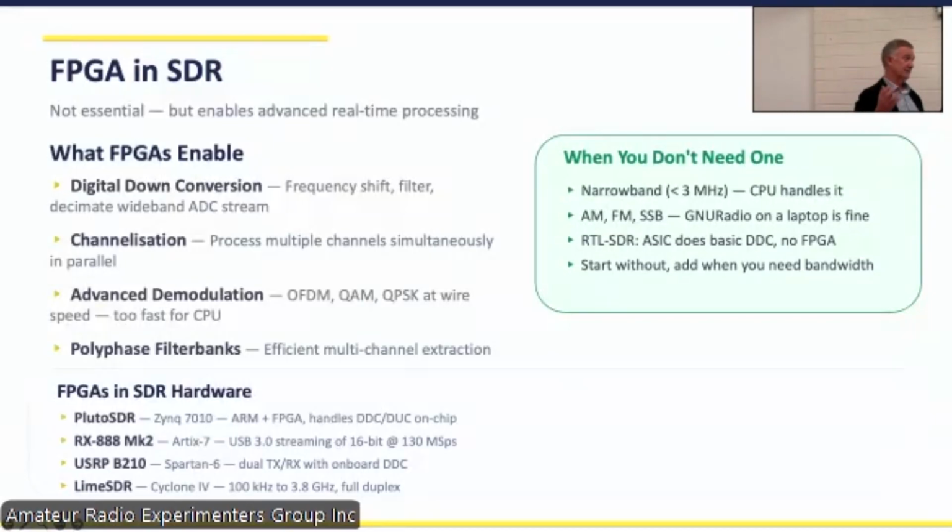If you want to take a 1 gig signal that, say, has 100 megs of data on it at the top, so from 900 through to a gig, if we're running in the IQ domain, we can multiply that by the frequency we're going to download it to, which is 100 megs below, and then filter it so it's only the first 100 megs of data.